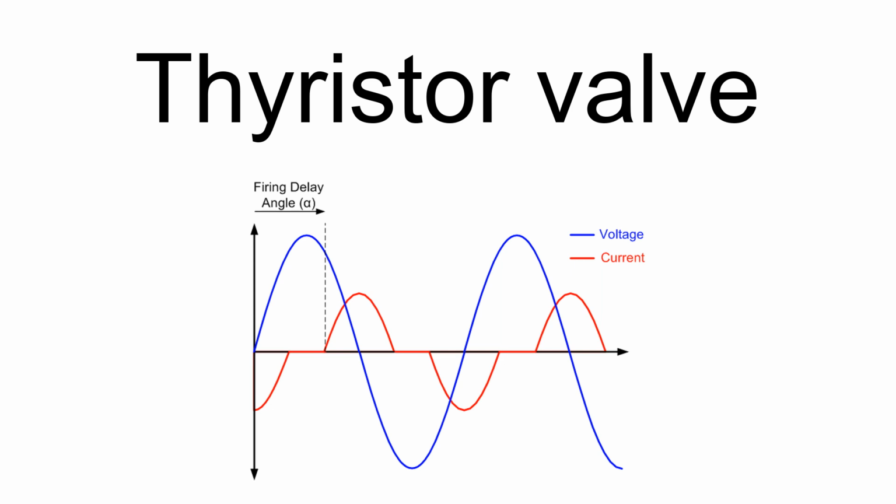In addition to the thyristors themselves, each inverse parallel pair of thyristors has a resistor-capacitor circuit connected across it, to force the voltage across the valve to divide uniformly amongst the thyristors and to damp the commutation overshoot which occurs when the valve turns off.